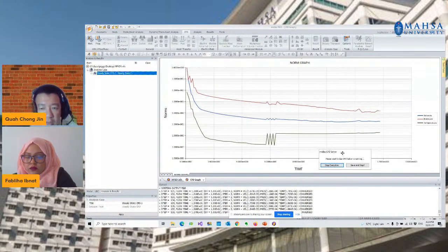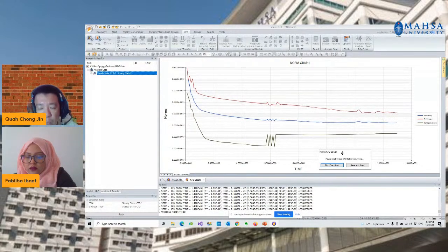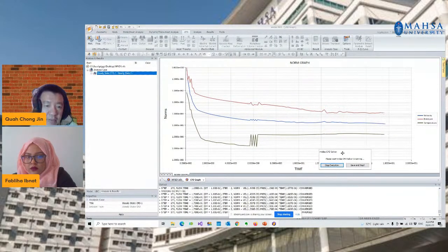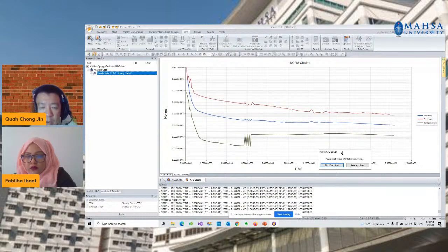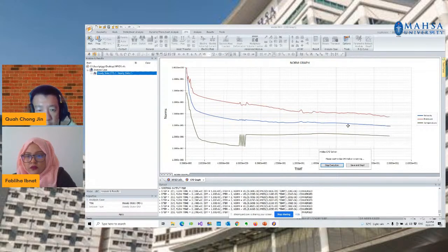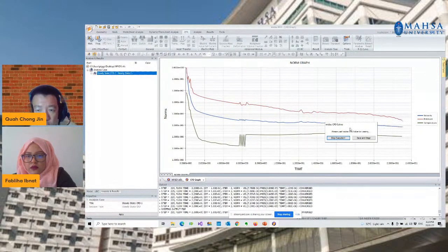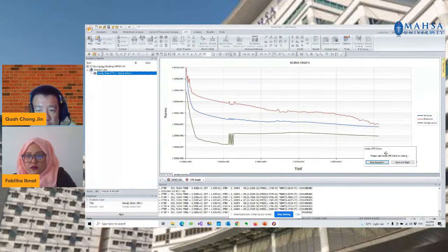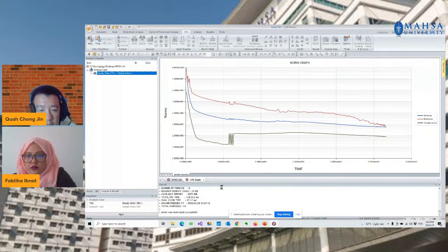And when we are doing the finite differencing, definitely we have some error. So we call it a truncation error. In this case, we call it norm or residuals basically, right? So before I proceed further to explain how the residuals work and how you can monitor the residuals, I just save and stop for a moment.